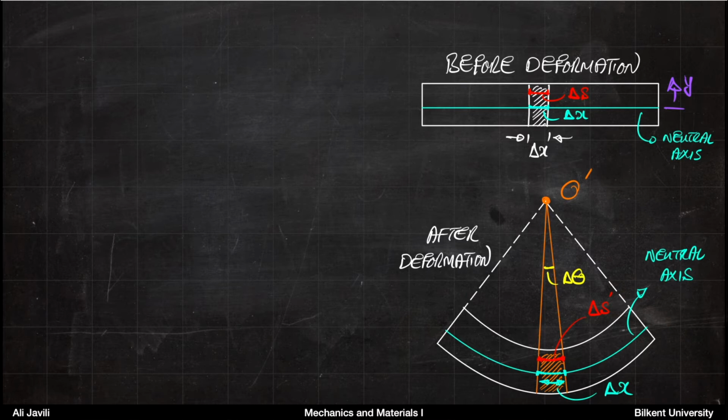And as I mentioned, basically the idea is that every cross section remains plane and remains orthogonal to the lines, meaning that this whole part would be an arc of a larger circle. So you can imagine that there is an imaginary center for that circle somewhere, and using that, you can define an angle delta theta to identify the length of each piece, or each piece of the arc in front of that delta theta angle.